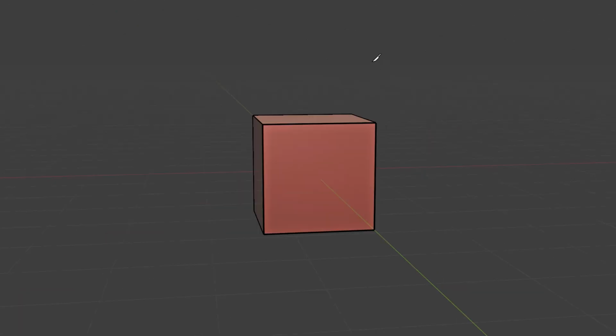There are two ways to start a knife cut. We can either hold the left mouse button down and drag the pointer, or click and release the left mouse button. Each has a slightly different effect on the cuts produced. Using the drag method, the normal practice is often to start the knife cut in an empty space, dragging the knife over the existing edge.